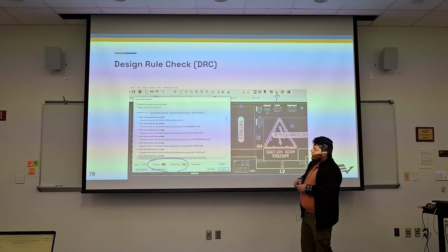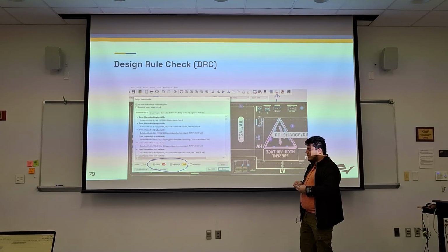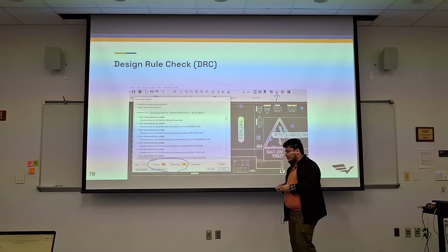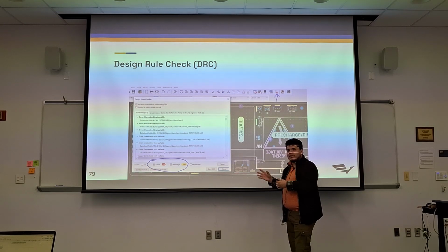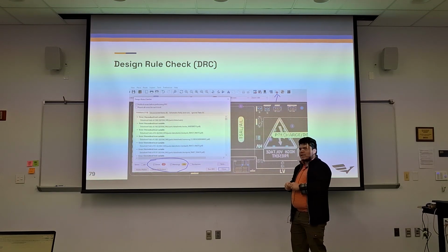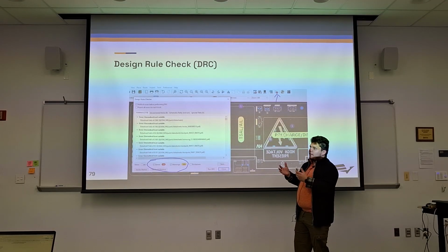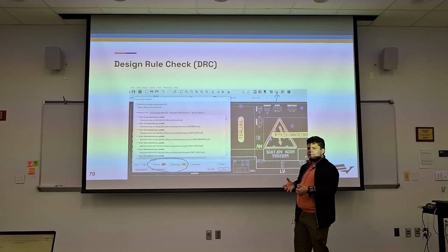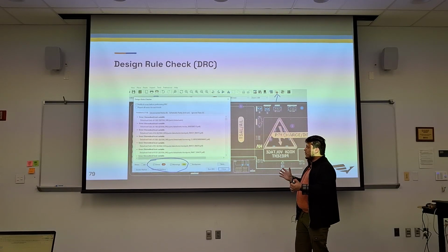This is a good start. Now, in industry, what we've realized is our EDA can only do so much. The DRC can only detect so much. What we do is actually check the Gerbers. In industry, we have something called the ODB++, which is an intelligent database that has the design. In this case, we're just using Gerbers.